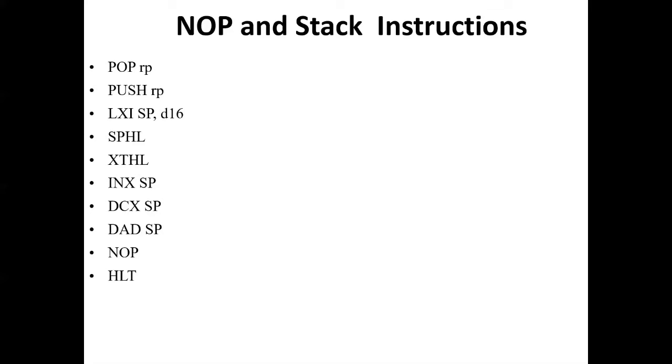Because of this advantage, SPHL can be useful when SP is required to be initialized to a specific value a number of times in a program. Now suppose HL had the value FB50H and SP had the value F900H. So after executing SPHL, SP becomes FB50H.